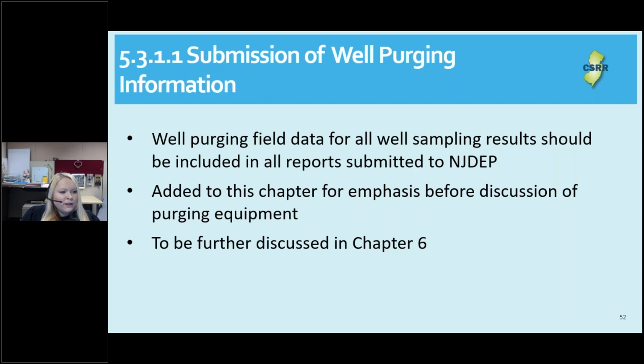Assessing the drawdown in the well intake interval is critical to evaluate the potential loss of pressure-sensitive compounds. Additionally, comparing the well purge rate to well drawdown data may allude to the well recharge capacity. Changes in the water quality parameters during purging show the difference in water quality within the well and the surrounding formation. The changes in water quality parameters should be evaluated when considering implementing a no-purge sampling method. Well purging information and well purge logs will be further discussed in Chapter 6 and Chapter 9.